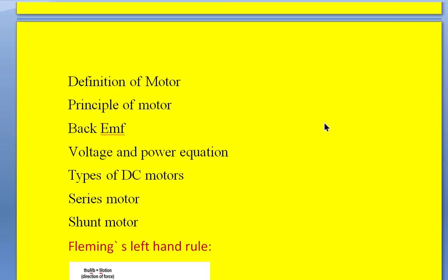And we have seen the resistance of the armature is less than 1 ohm. Similarly, in the case of the DC series motor, the series field winding resistance is also very small, that is 0.05 ohms, whereas the shunt field winding resistance varies from 100 ohms to 250 ohms.